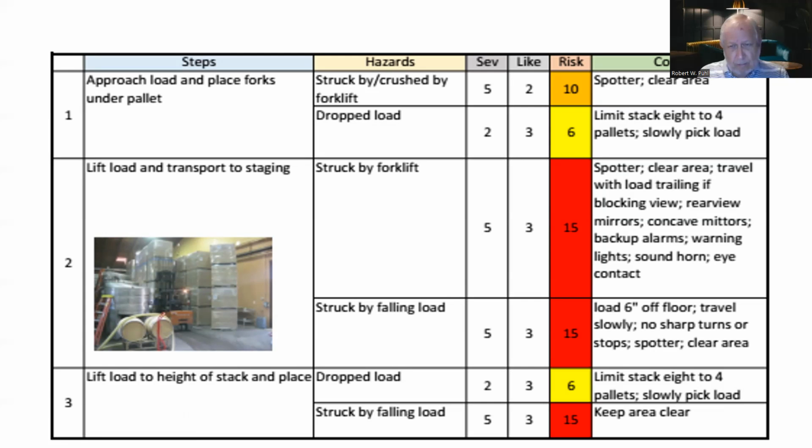Hazard: drop load. Limit stack to 4 pallets. Slowly pick up load. Okay. Now you get drop load. Now you can limit it. That's a good idea to limit the height. Just the higher you get, the less stable it is.